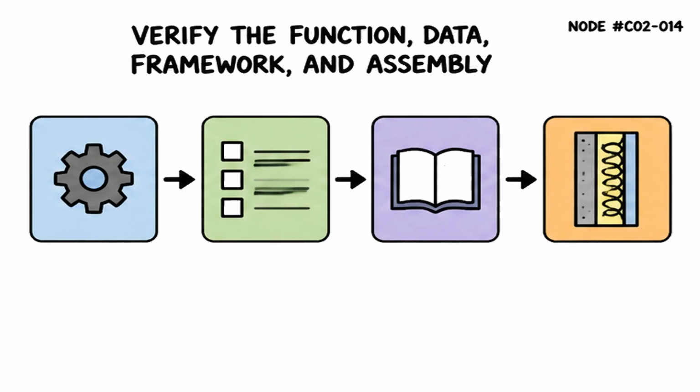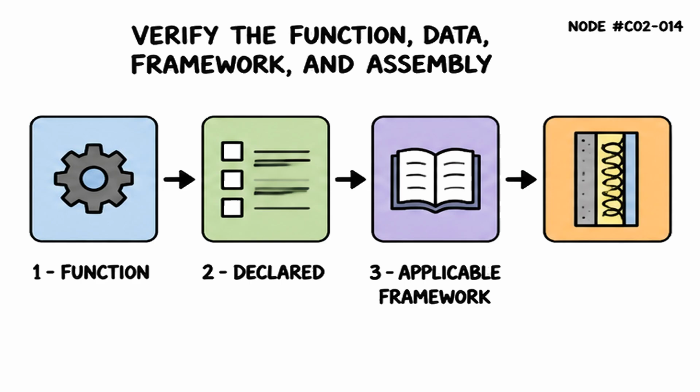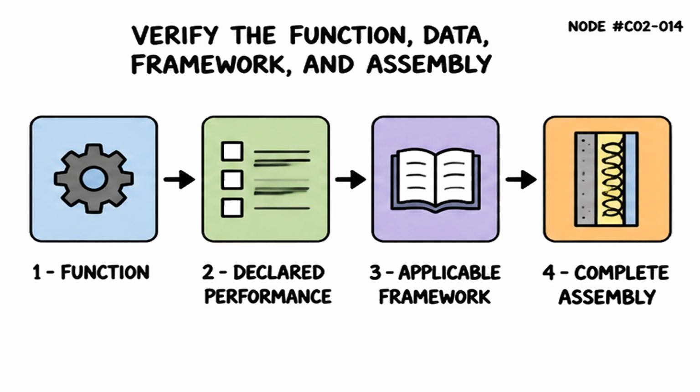Use 4 questions to examine the evidence. What function is claimed? What performance is declared? Which framework and conditions apply? How does the complete assembly manage air, vapor, rain, and drying?